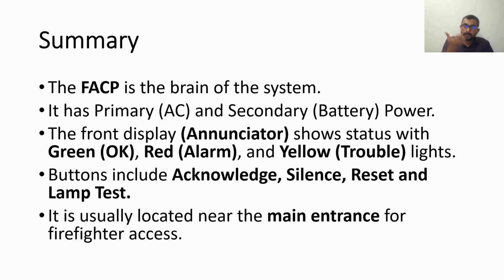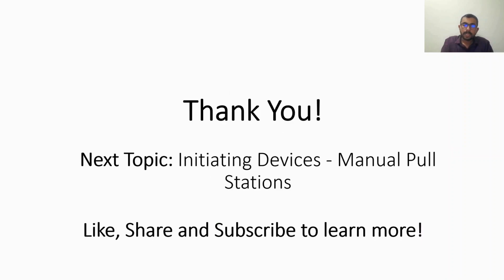Then we have discussed the location of the control panel. Whenever we install, we ensure that we install it near the main entrance or in an area where the firefighters can access. Like what we have discussed, normally the fire alarm control panel is kept inside a room called the fire command center. So we have reached the end of the episode, which is about the fire alarm control panel.